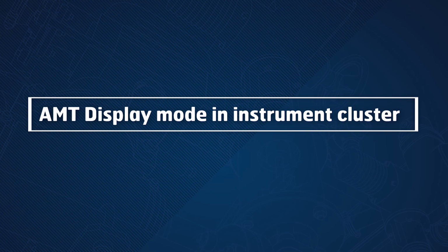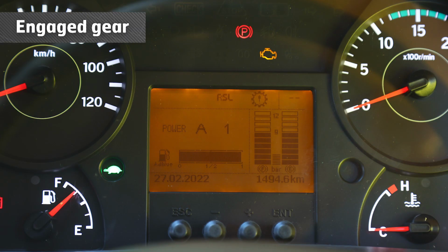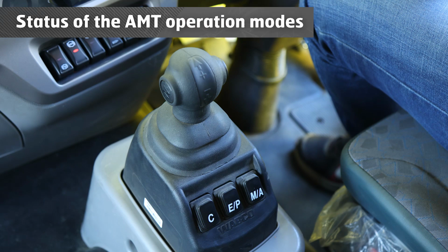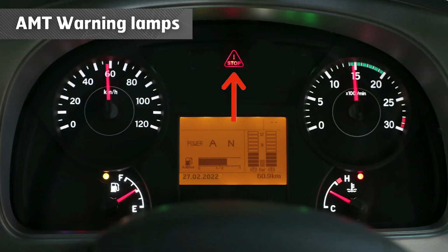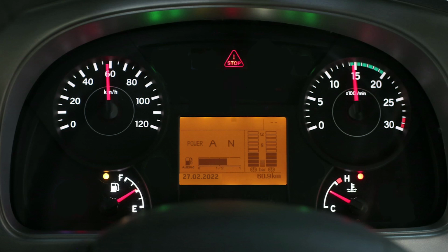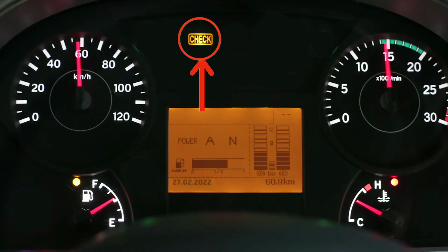AMT display mode in instrument cluster: engaged gear, and status of the AMT operation modes: automatic or manual, power or economic, or crawler. AMT warning lamps. Stop lamp: the vehicle has to be stopped immediately and the AMT failure has to be repaired before the truck is operated again. Check lamp: vehicle operates in a reduced functional mode. AMT failures should be repaired as soon as possible.